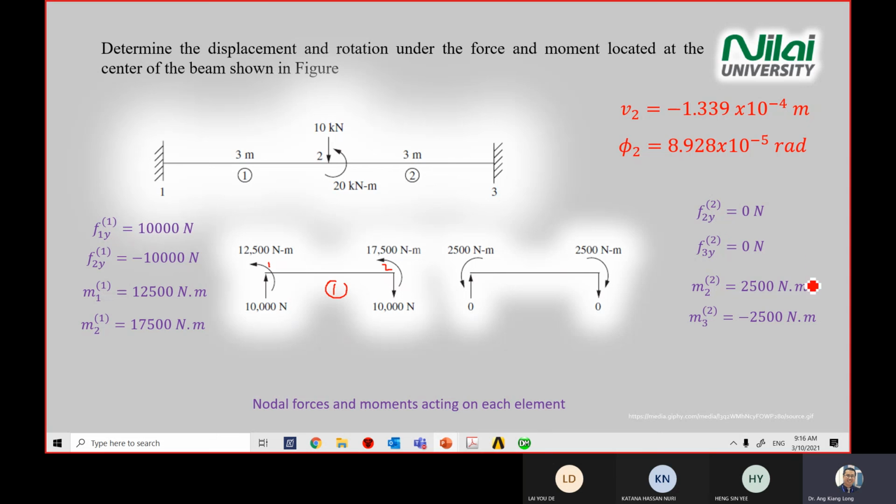Element 2, you look at the answer over here. So you have 0 forces in the element. So you just put 0 and then put arrow there, right? How you know the arrow is actually come from the previous, his neighbor, where if you look at element 1, is going down. So there will be a counter direction. It will be going up to counter the force over here. So you draw up, although it's 0, but the direction we assume that it will be a coupled effect where it will be opposite direction of the neighbor. So the next one, although it is for point 3, although it is 0, the direction is also coupled to balance the beam. So one go up, one will go down.